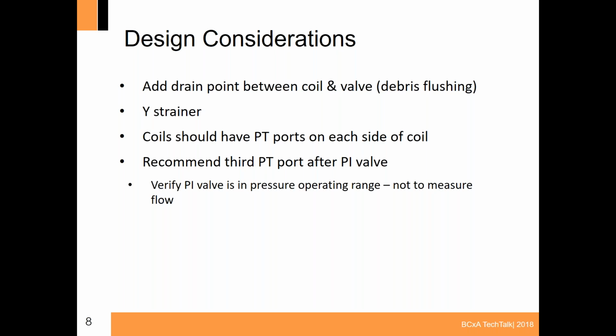So one of the things when you go through to check and make sure on the commissioning side is, do I have that minimum pressure at my valve? And then if I verify my pressure independent valve is in the right range, as long as we have that minimum pressure, you know that valve is going to operate properly.